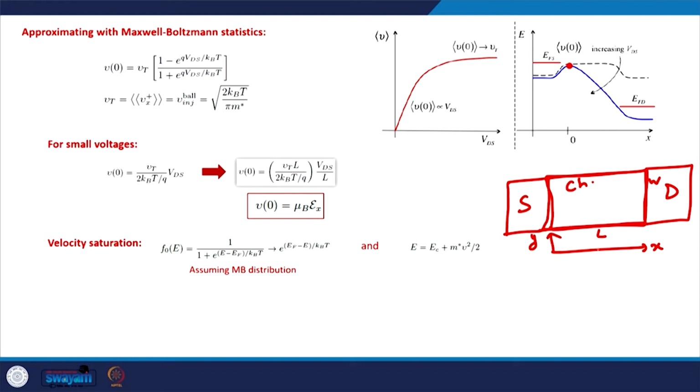distribution of velocities. Whenever an electron starts from the source side to go to the drain side, what is its Vx, what is its Vy, and how are these velocities distributed for various electrons in this device? That's what we need to understand, and we will start with the Fermi-Dirac distribution function in order to understand that. So the Fermi-Dirac distribution function says